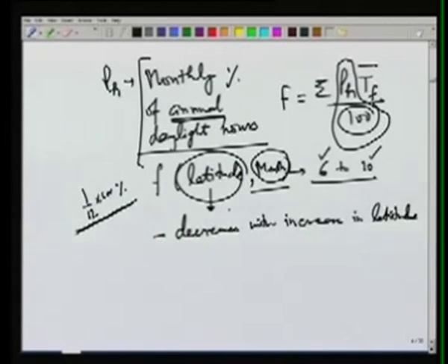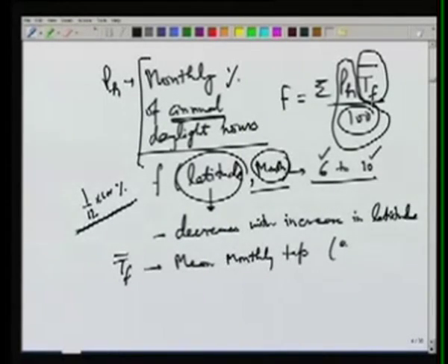So this fraction p_h, and then we have this T_F bar. So multiplication of p_h and T_F bar is summed up over all the months, then we get F. T_F is the mean monthly temperature, and it was used in degree Fahrenheit in the original equation, so we will keep that degree Fahrenheit.